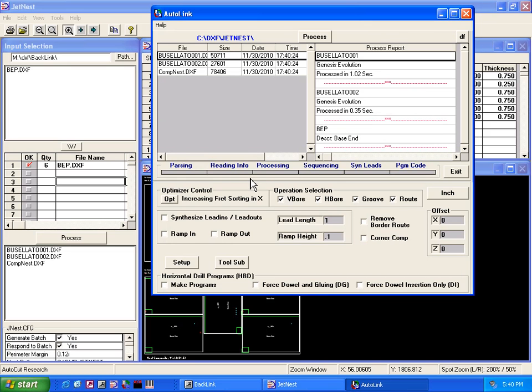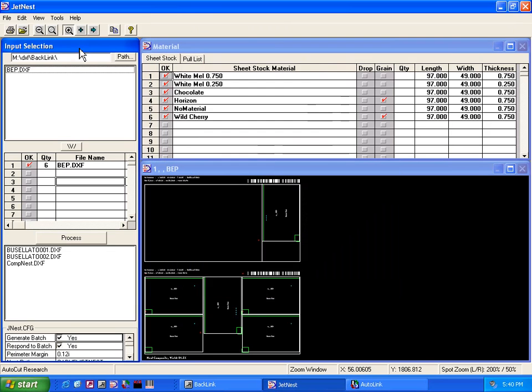So just check all those settings. If something's not going seamlessly from one program to the next, then just double check that each program is creating a batch file, and that the next program is responding to it. And then the most common problem is that the folders are not set to be the same as the program before it. So just check all those things, but once those are set correctly, then all the processing happens seamlessly.